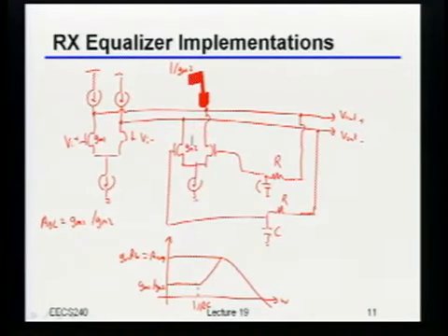We said that at DC, that feedback connection there creates a 1 over GM, right? But now, usually we ignore ROs. Let's not ignore RO this time. So at high frequency, what's the maximum impedance you'd see looking down into there? And by the way, when I say high frequency, I mean so high that the low-pass filter gain has gone to 0. RO? Yeah, it'd be RO, right?